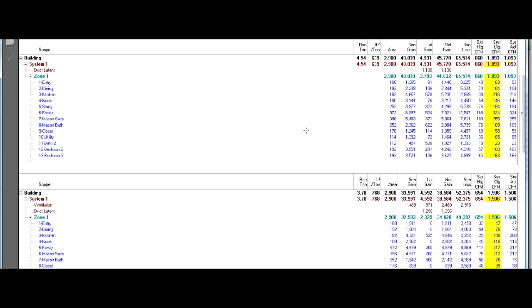Now what I want to do next is compare that 2012 house to the retrofit house that we did previously. If you haven't watched my previous video, previously I took a 30-year-old, inefficient house, and we turned it into a highly efficient house by replacing the aluminum windows with vinyl windows, and by moving the duct from outside the conditioned space to inside the conditioned space, or making the attic a conditioned attic. So I want to compare this and see how much better the 2012 is.